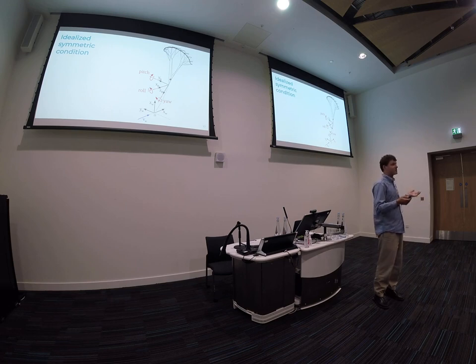And why is that important? Well, if we're trying to resolve this problem in a simulation, we essentially need to solve the 6 degrees of freedom. So 3 translational and 3 rotational. And then we need to find convergence over each axis. And by assuming this idealized symmetric condition, we can reduce those 6 degrees of freedom to a mere 1 rotational, namely the pitch, and 2 translational over the Z and X axis.